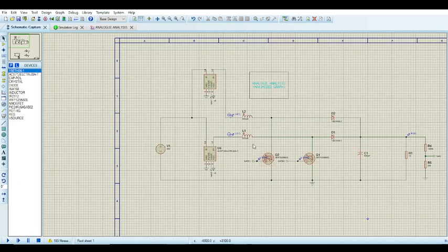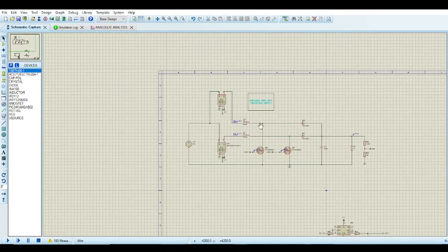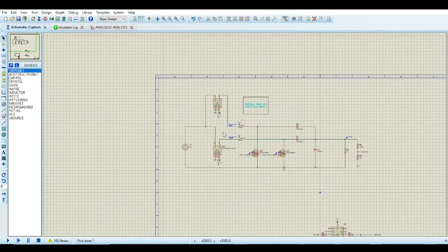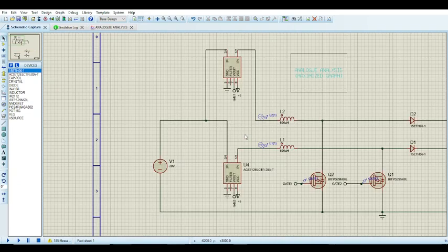And what else did I want to say about this? Yes, in terms of the importance of the hardware, those things are important and need to be connected properly. Everything, like I said, inductors, one can go coupled, and having to design a snubber to counteract that effect of the coupled inductor leakage inductance and all that. The hardware is super important. And secondly, the sensor placement. The sensor placements are important, and it depends on your goal. Are you trying to go for high efficiency? If you're going for high efficiency, then you have to use a Hall effect sensor.